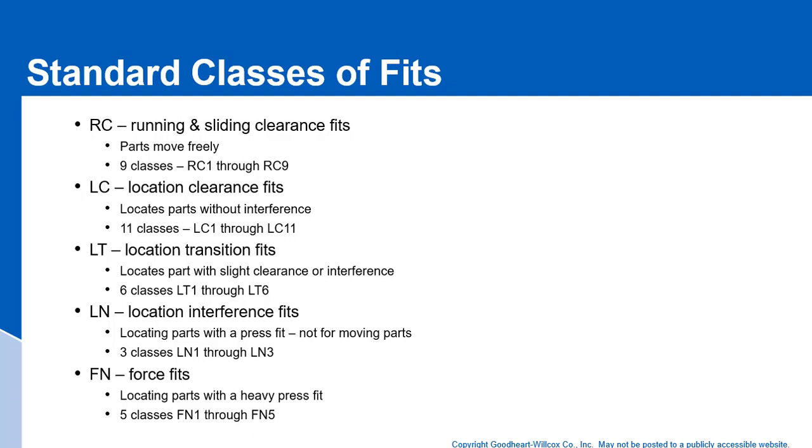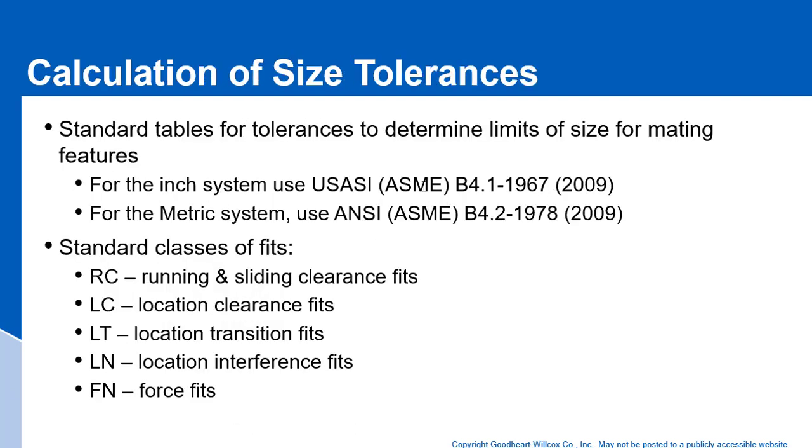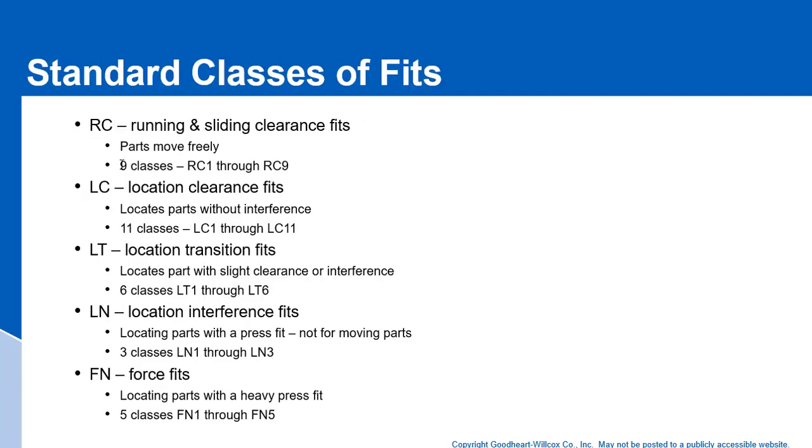Hi students, briefly to continue about our fits, these would be the list of the fits, and per those tables that we were talking about here, this would be the ASME B4.1 and 4.2. There are 9 classes of RC fits, there are 11 classes of LC fits, there are 6 classes of LT fits, 3 classes of location fits, interference fits, and then 5 classes of force fits.